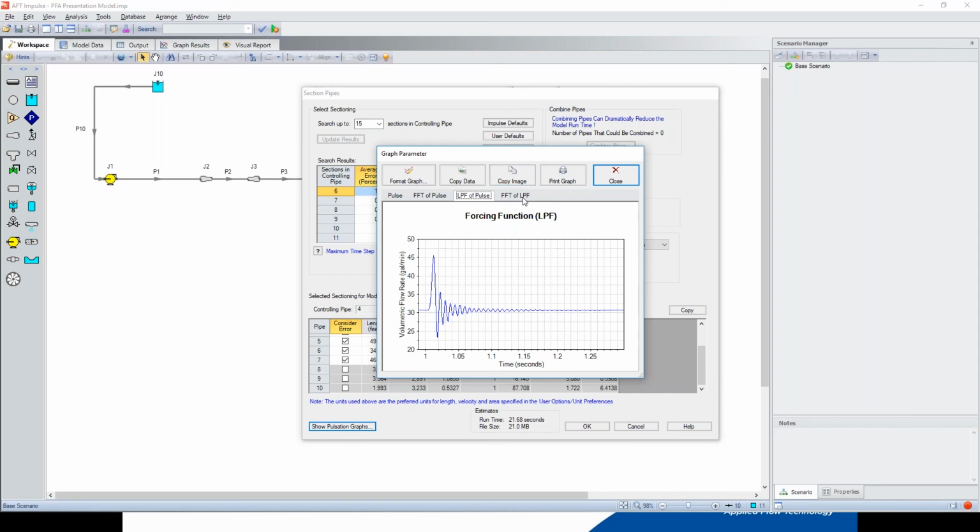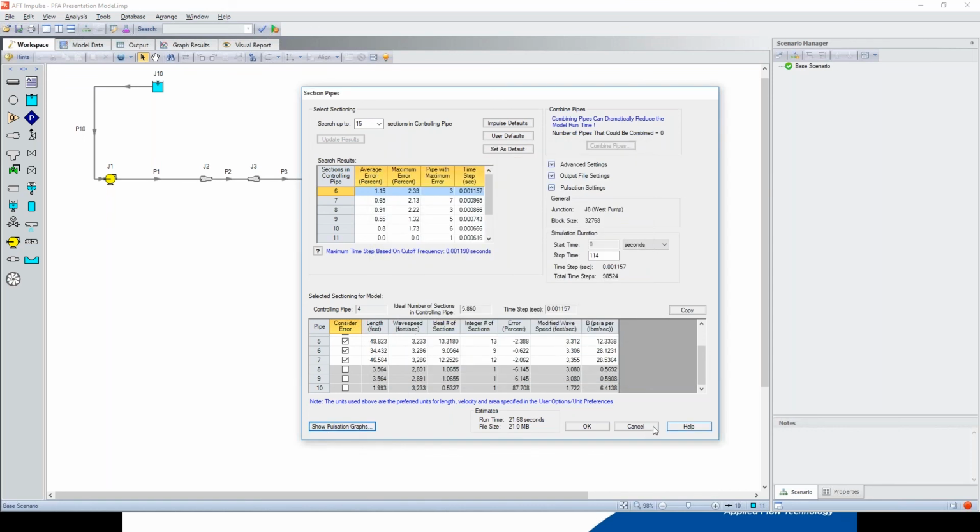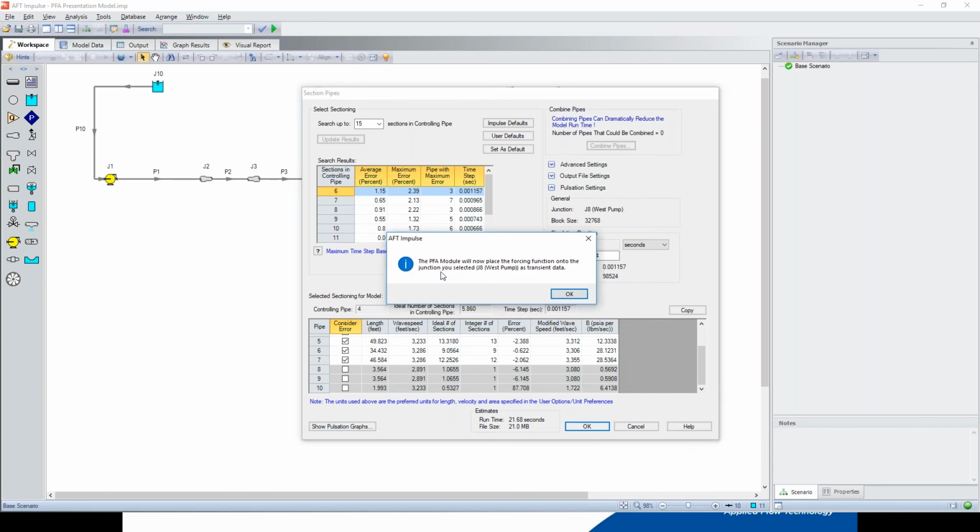of the PD pump. It's going to be operating at 120 RPM, and we enter all the physical data: the bore, the stroke, the rod length, the clearance, the suction pressure. So it can calculate the pulsation that is going to be applied when we model the system to check it with API 674. Once we do this, we come to the analysis tool and we go to the sectioning. So we will section the pipe based on the frequency cutoff.